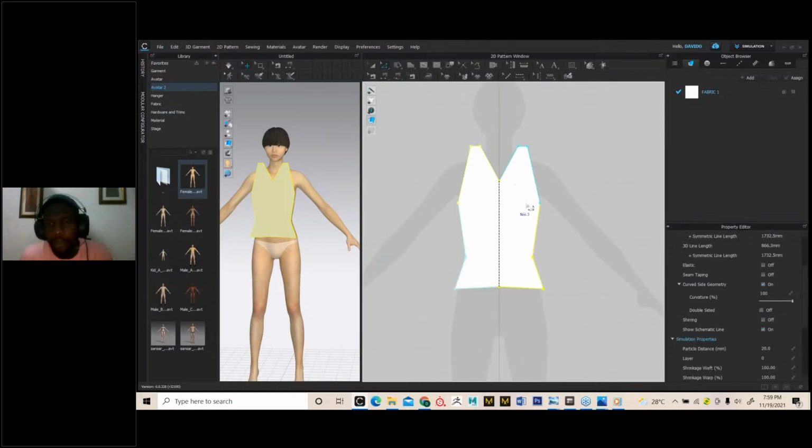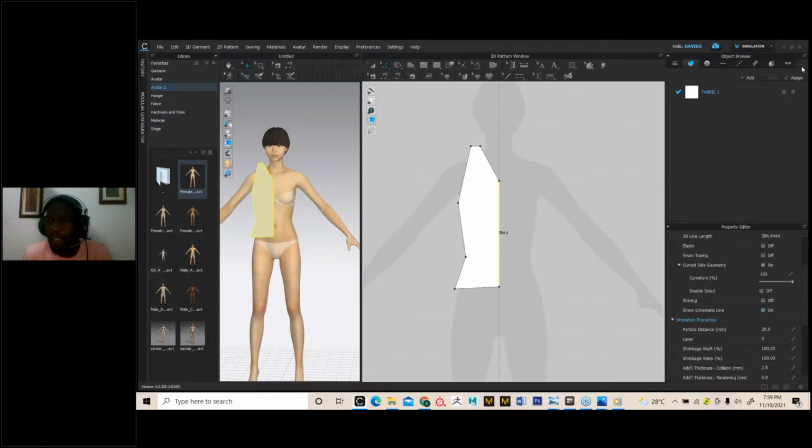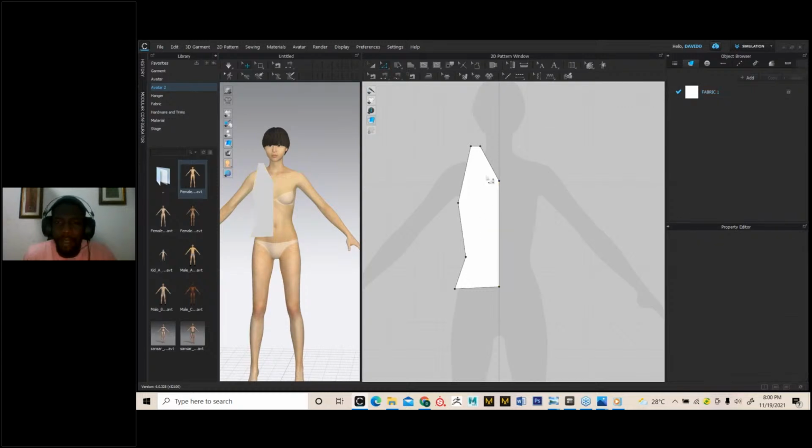So don't worry about the action I performed right now. We are still going to go there. I'm going to take you through all those processes. So that's what your polygon tool does. Your polygon tool simply allows you to draw out your shape the way you like. So once again, to use your polygon tool, you left click at the point you want to start drawing your pattern. Then you continue drawing. You click, control, click.